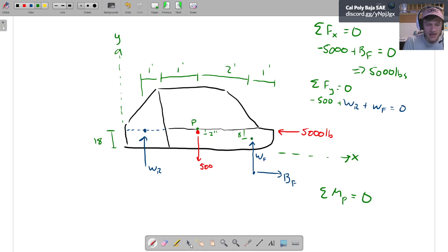So I can slide this vector up to the shock. Because in this example I removed the wheels, I can say that this braking force is applied just at the location where the shock's attached to the chassis.